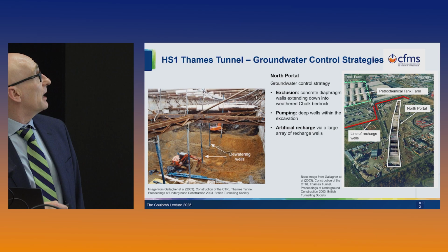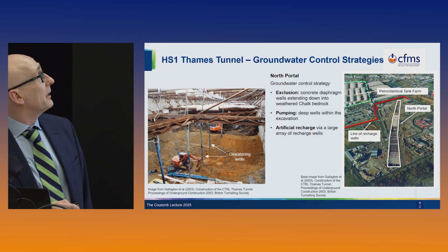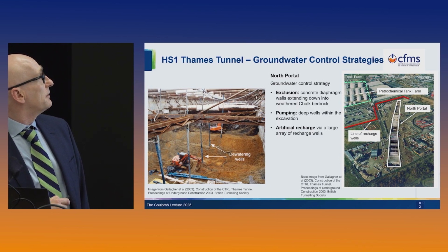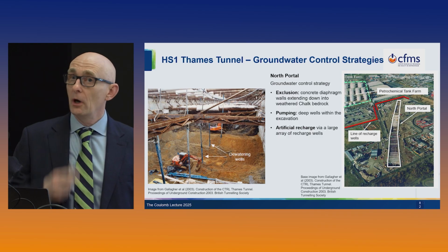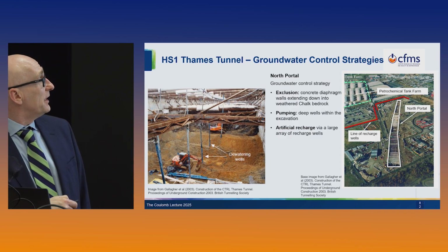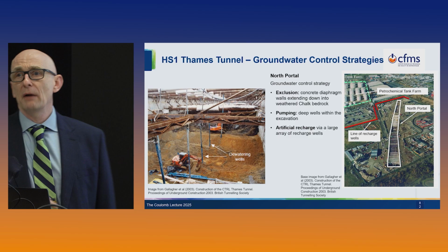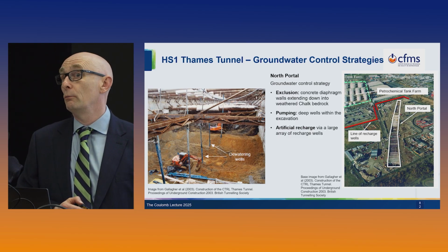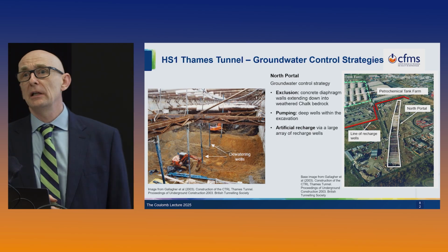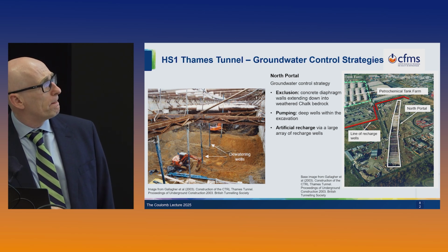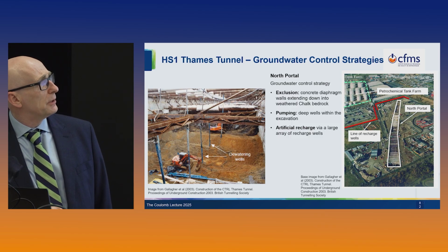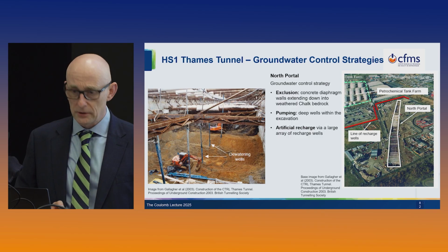This is an image here of inside the excavation. We have the concrete diaphragm walls out here, the big props. These vertical pipes are the dewatering wells, and this brown stratum is the gravel of the river terrace deposit. For scale, this excavator here is sat in the dry, and that's probably roundabout 10 metres below original groundwater level that we've dewatered, and I think it probably went down nearly another 10 metres later on. And again here, this is the north portal, this is the sensitive tank farm that's been protected, and this red line are the recharge wells where we're re-injecting the water.